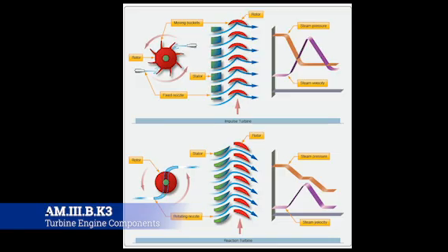Now the reaction turbine blades cause the disc to rotate by the aerodynamic action of the airstream directed to flow past the blade at a particular angle in order to develop the most efficient power from the turbine engine. The reaction impulse blade combines the action of both the impulse and the reaction blades. The blade has more of the bucket shape of the impulse blade at the blade root, but it also has more of an airfoil shape of the reaction blade towards the tip. So that is how those blades work.